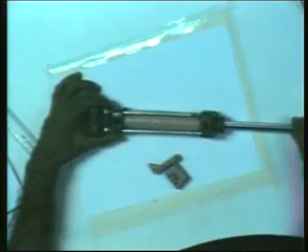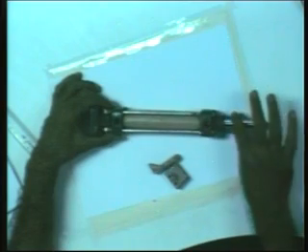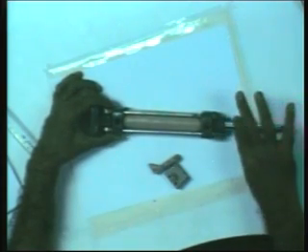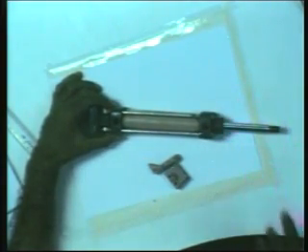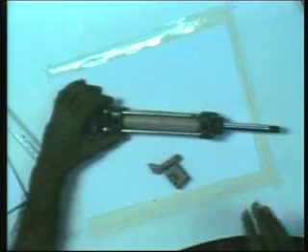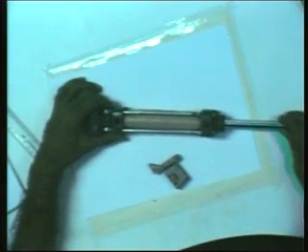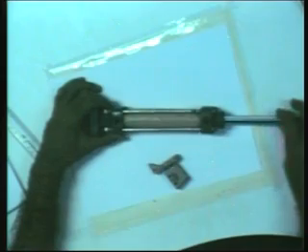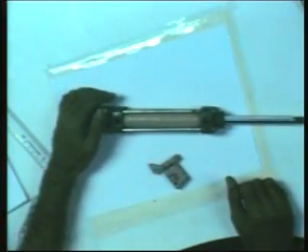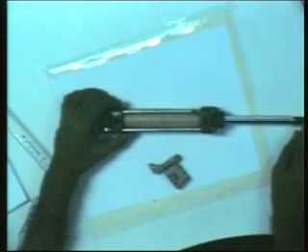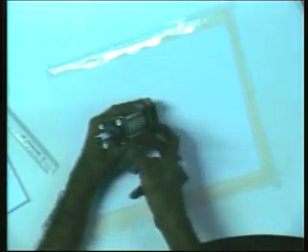If you want to change the stroke, you put a ring out here. So when you come back, when the ring hits the front face, it stops. That's the only thing you can do with these pneumatic actuators. Lately, people have been trying to control and see whether they can attain intermediate position. This is because air is compressed. Pneumatic cylinders are not stiff. Supposing I put a weight on top, though I admit air, because of the compressibility of the air, this will go down slightly because they are not stiff.